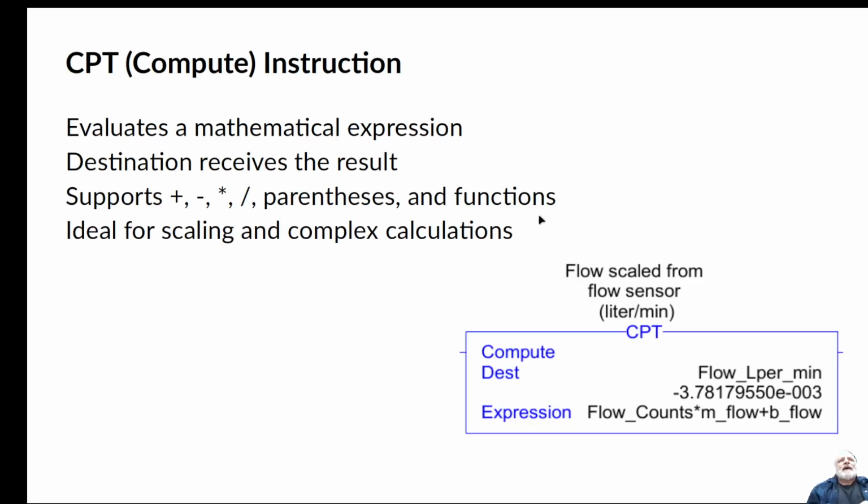All right, we also have compute instructions. If you just need to multiply or add, they do have add, multiply, or divide blocks, but that only does one calculation. If you need to do more than a simple one calculation, then you need to use a compute statement. So in this case here, this was for a tank sensor and tank pump, and I'm counting how much data is flowing.